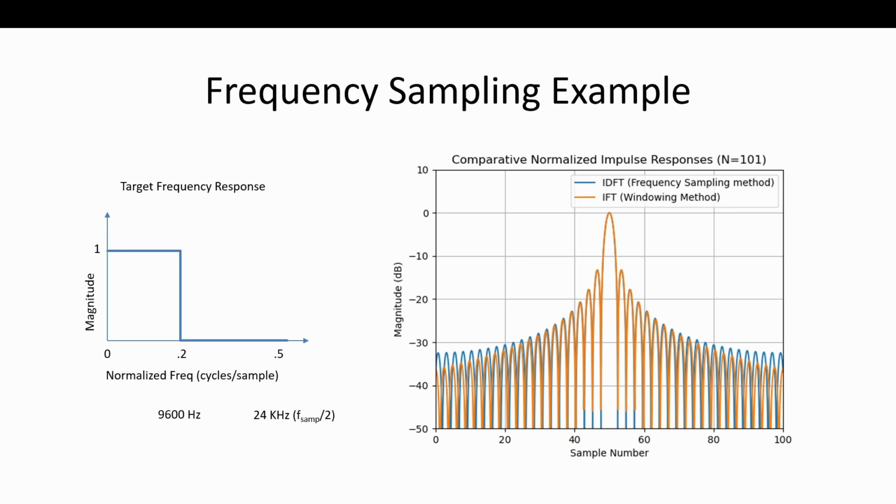But you're seeing in orange or red here, that's the sinc function. This is a pure sinc function in terms of the magnitude of it converted to dB, and it's truncated. It keeps going like this, right? So our error in that case, using that one as the filter, is the truncation error. And I showed you all about what that is.